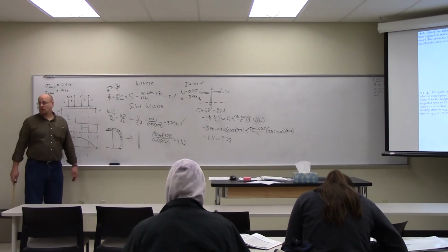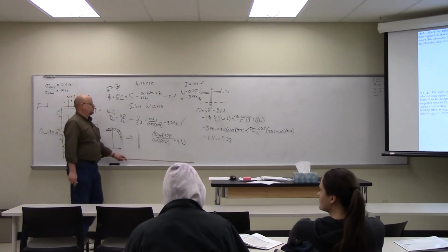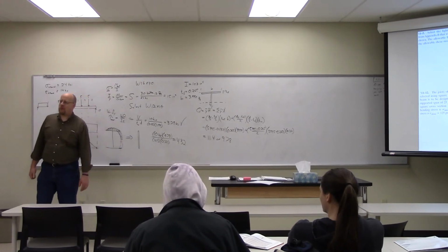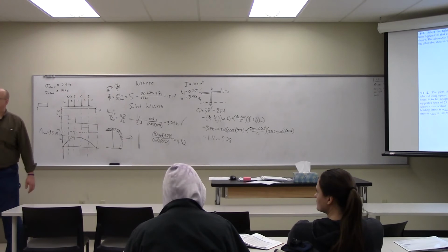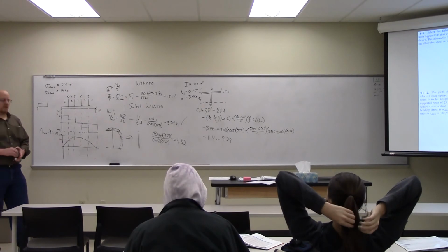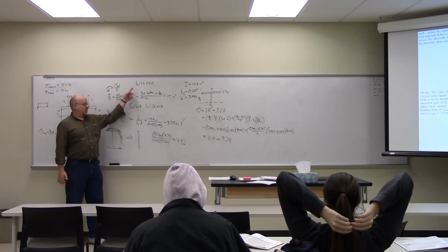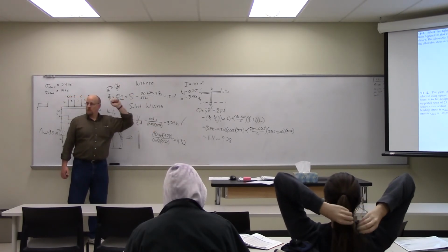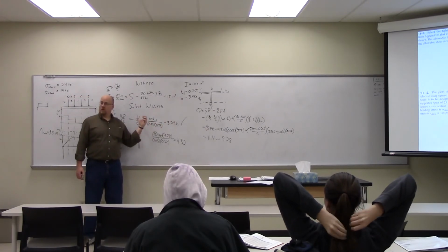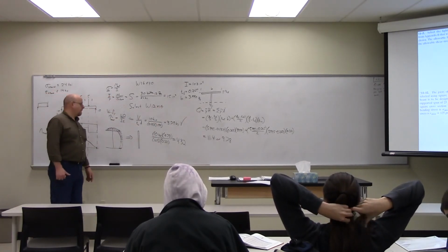But on the test, you want to make sure you rationalize that. If on a test you're just asked for the beam design, we wouldn't technically have to go further. But if you had specifically asked how close it was, then we would. If I ask for the maximum shear stress, you do the real deal. If I'm asking for the beam design, you verify that this is good, and say this is well below, so this approximation indicates that it's still good enough. The approximation is technically over engineering it, right?